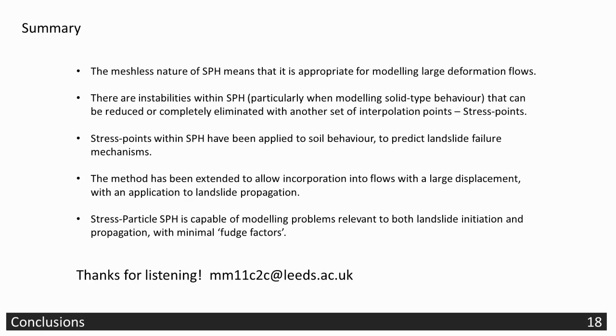So just to conclude, SPH is a really useful numerical tool for solving problems involving large deformations, which are relevant to both landslide initiation and propagation. But there are some instabilities that you see in SPH, particularly when trying to model the initiation phase, which exhibits more solid behavior, that can cause severe failure of the problem. But having the stress points in the method can either completely eliminate or reduce these instabilities. And we've extended the method so it's also capable of being applied to flow type problems and the propagation phase of landslides. So it's bridging the gap for a numerical method between landslide initiation and propagation. Thank you.